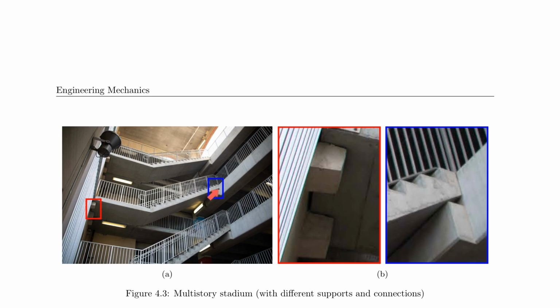So engineers want to make sure that if, for example, this part of the structure is exposed to heat and it extends or changes its shape or its dimension, that it still does not affect this part of the structure negatively. So this portion has to be somewhat decoupled from this portion, and the way engineers deal with that is with, for example, neoprene pads that then create a certain type of support reaction.